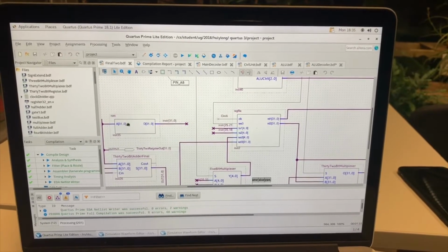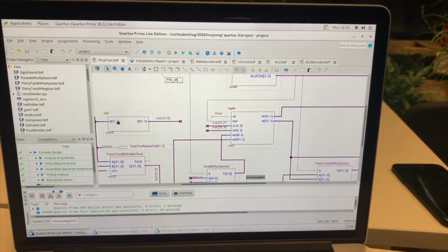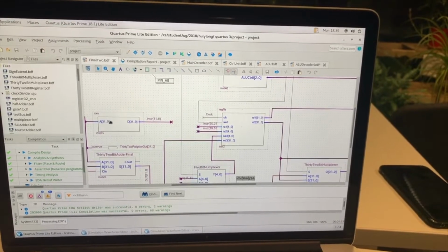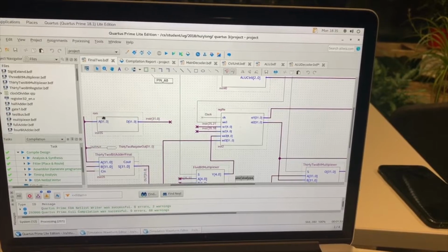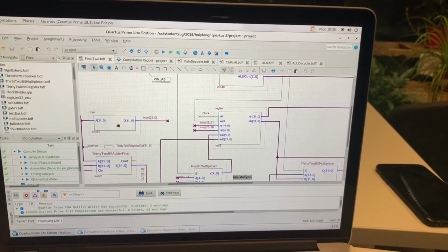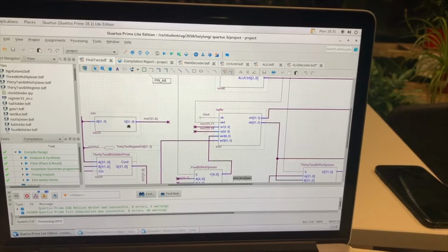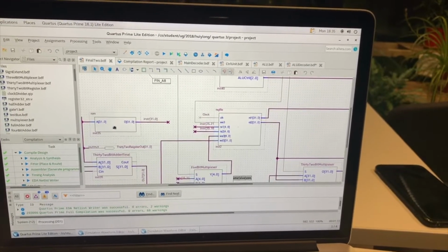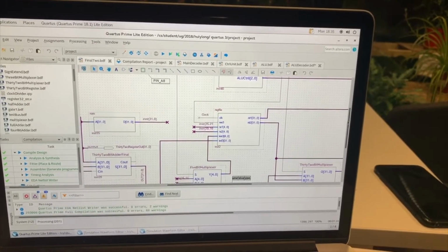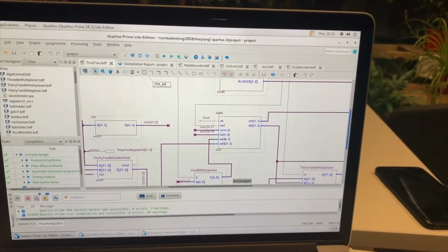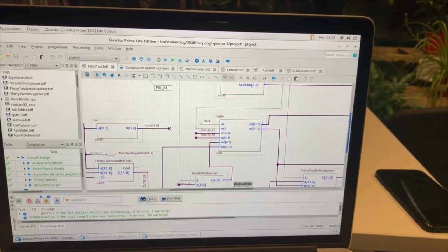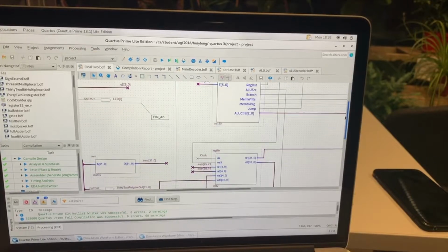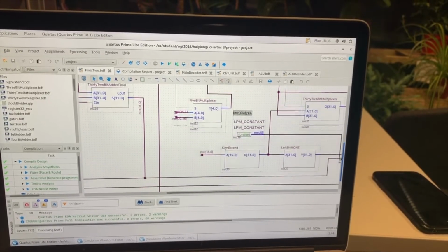Moving on, we talk about the ROM. It is where all the instructions of a program are stored. It is an instruction memory. Here, we use assembly language to write our squares program that will be shown and explained later in this video. We use three different types of instructions in our ROM, namely R-type, I-type, and J-type. All of these different types of instructions have different bits assigned to them. The ROM then transfers the instructions to the control unit, the reg file, and the sign extend.